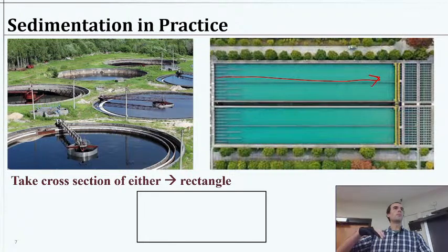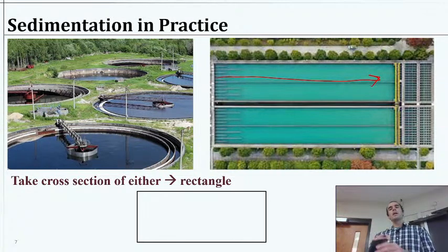It'll stick to the bottom. Then we later will scrape all the particle junk and collect it, maybe with a little vacuum sort of thing. We have some mechanical way to collect that stuff off the bottom. And meanwhile, continuously the water will be collected off the top into the next chamber for treatment.